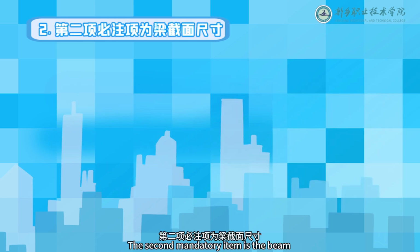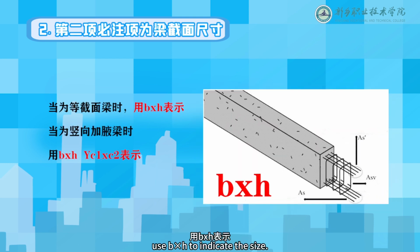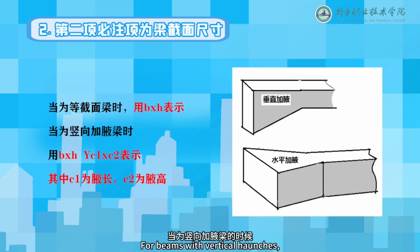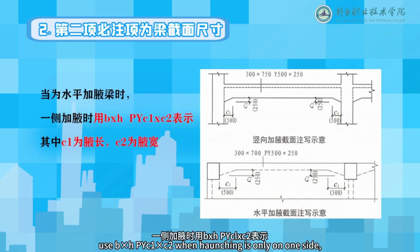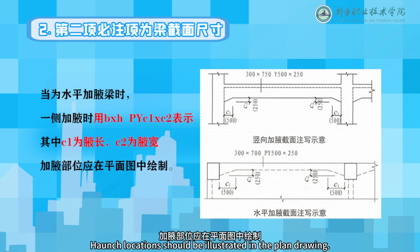The second mandatory item is the beam cross-section dimensions. For constant section beams, use B by H to indicate the size. For beams with vertical haunches, use B by H, YC1 by C2 to indicate, where C1 is the haunch length and C2 is the haunch height. For beams with horizontal haunches, use B by H, PYC1 by C2 when haunching is only on one side, where C1 is the haunch length and C2 is the haunch width. Haunch locations should be illustrated in the plan drawing.